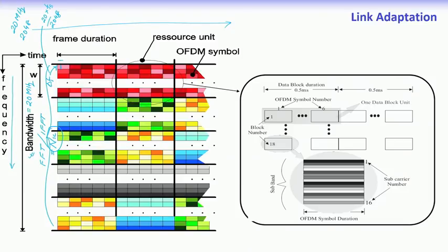And this is the OFDM symbol duration, which is T s, which is equal to T g i plus T u, sorry, T u or T f, it is the same thing, right. So, now we have to send signals over this. So, as we have said, each one of these small rectangles, they are usually called resource elements, resource units, or resource elements.